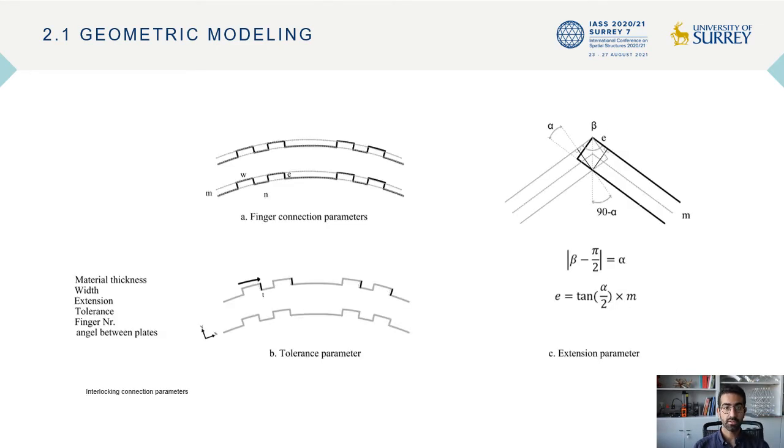A special focus in the development of the two-dimensional finger joints lies in construction, the structural performance, and assembly details. Parameters such as number and the depth of the finger joints are determined based on the edge length and material thickness respectively. Another crucial parameter of determining the width of the interlocking connection is the correct definition of tolerance in the curved configuration.